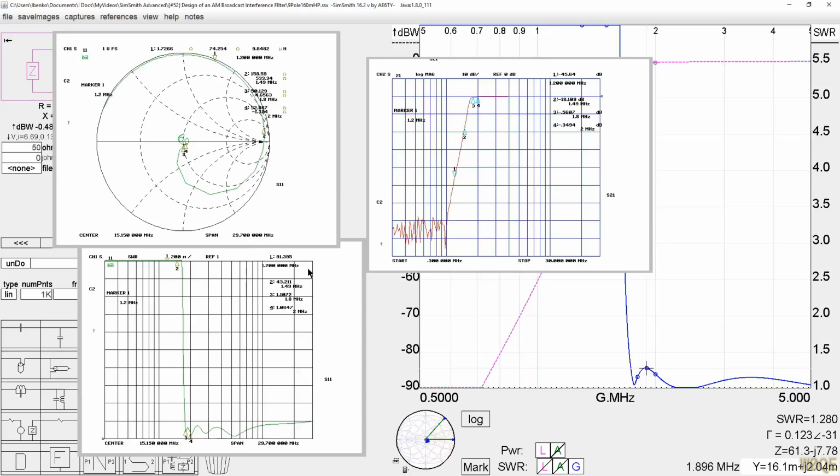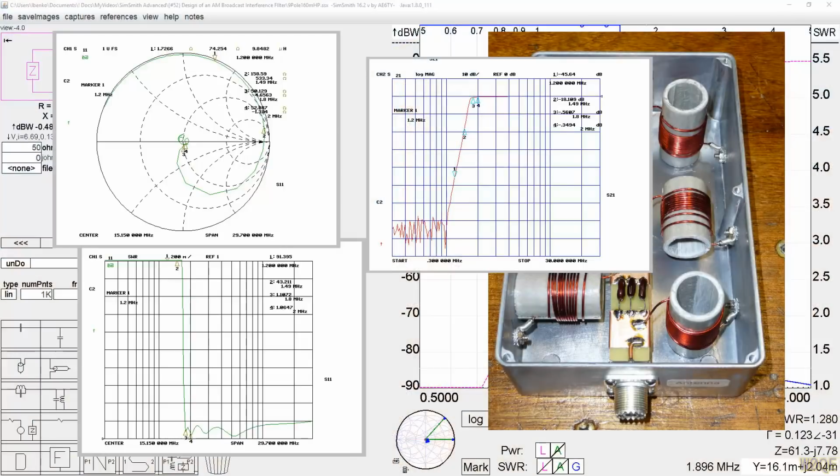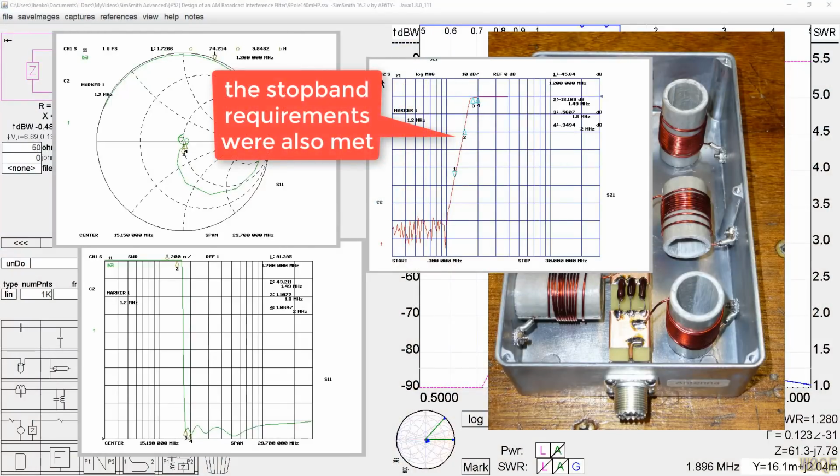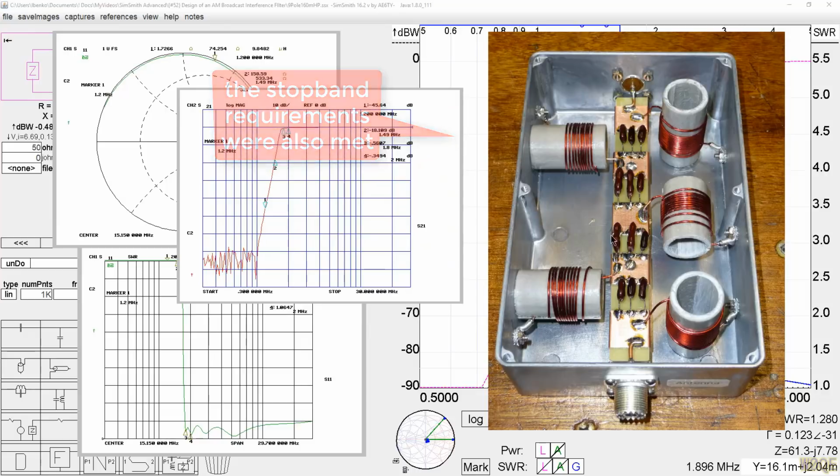So anyways, it's got a good SWR. It matched what we tried to design, and I would attribute that primarily to the fact that this is large. These inductors had pretty high Q. They were measured and tweaked turn spacing wise by putting a network analyzer cable in here.